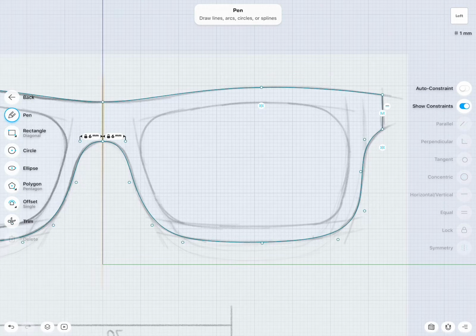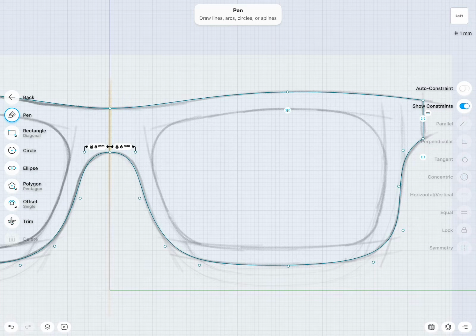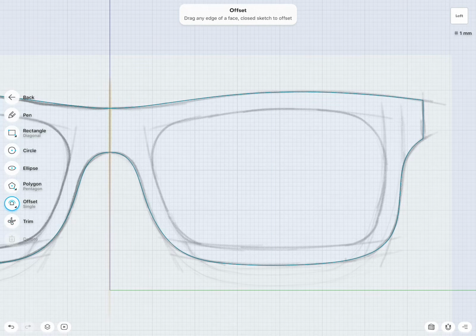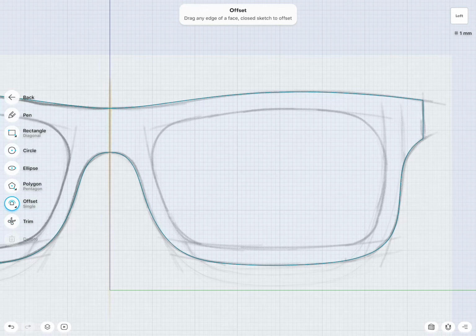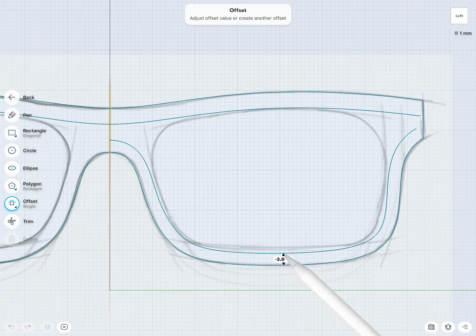Okay, so let's take a look at the opening for the frames. So what's the best curve here to select? Again, I gave both curves a test, but I found that the CV curve simply is better. Similar case, more points, but then I have more control. But before I continue, I want to go offset and click this one and say single. That's what we want. And I will make an offset here. And I will do the same with this one.